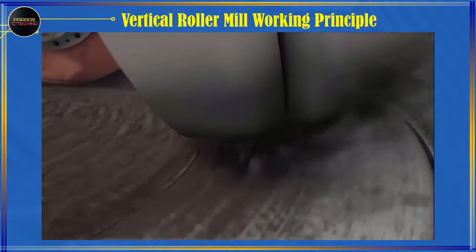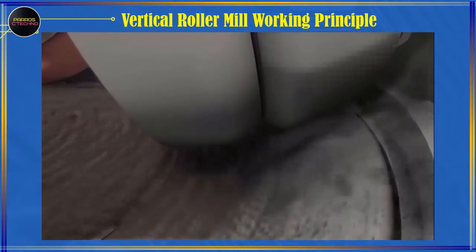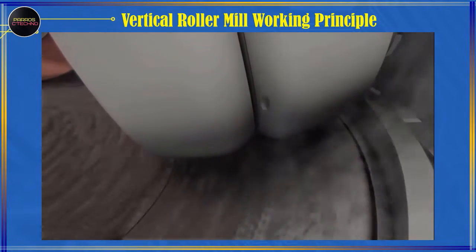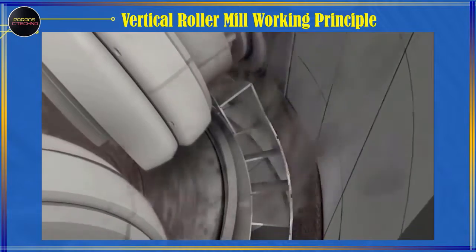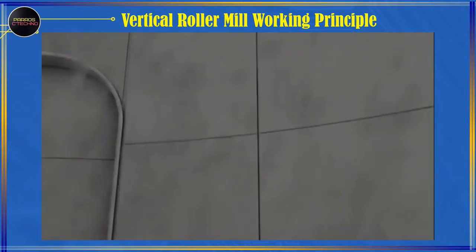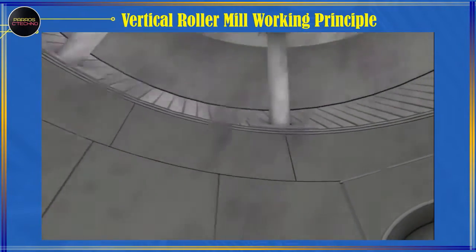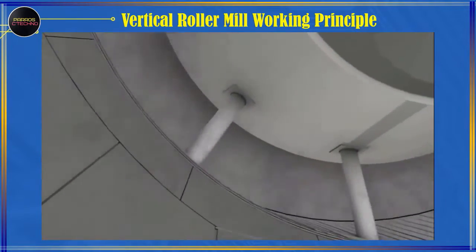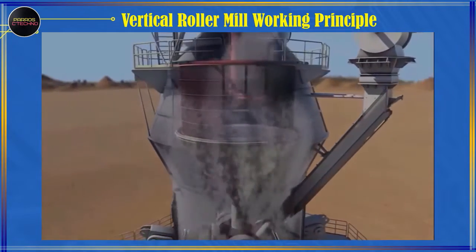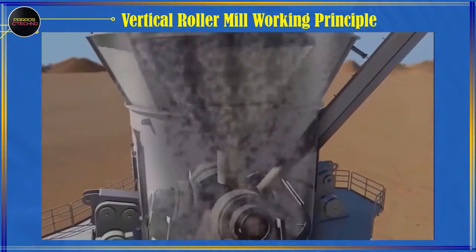The inner part of the patented grooved roller profile evens out and consolidates the material before it continues to the next roller. The outer part creates highly concentrated grinding pressure, allowing air to escape through the middle ground. Partially ground material passes into the hot gas stream, which also provides drying capability, and moisture in the material evaporates almost immediately. The separator allows material that has reached the required fineness to leave the mill, while it rejects oversized material and sends it back to the table for further grinding.